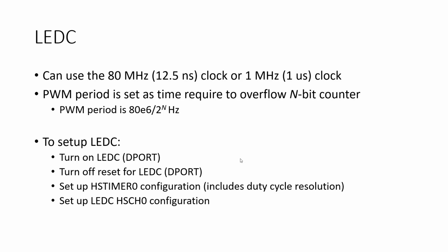Actually, we simplified, this counter is actually a fixed point counter. Is this the fixed point number? Yeah, so there's a fraction. It's the clock divider that goes into the counter. Oh, yeah, sorry, that's what it is, the clock divider. I'll get to that. So anyway, the point is that I don't think it's really important what you set the clock frequency to. It just has to be high enough, but it's indirectly set.